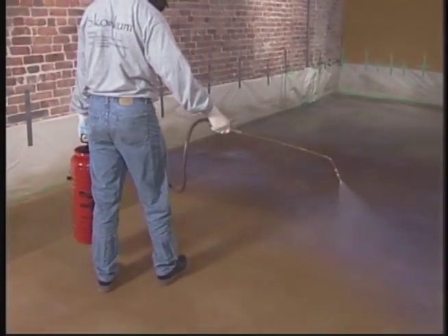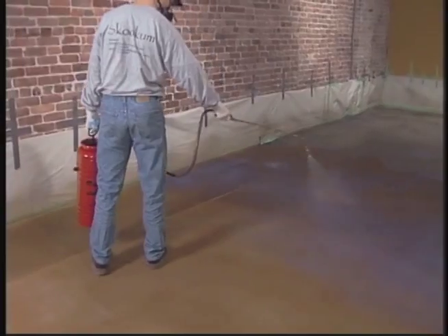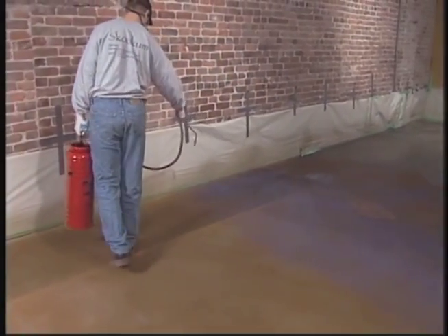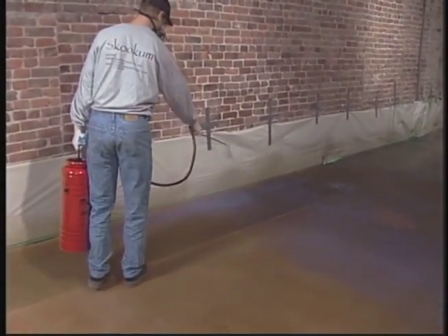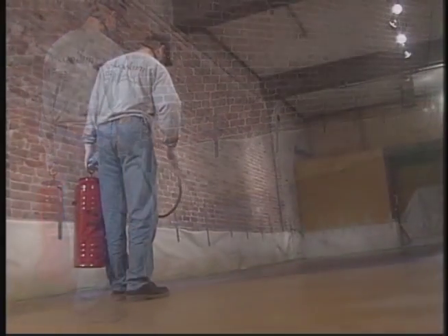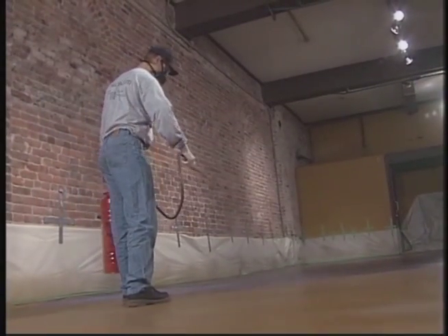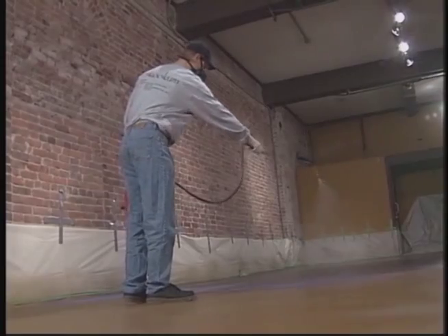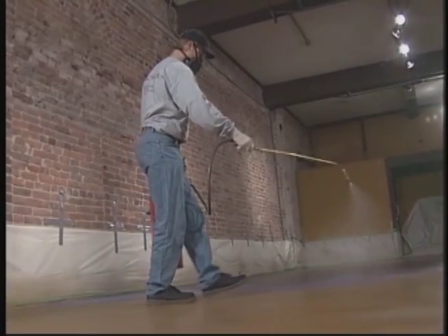The primer or first coat of any application sets the standard for all subsequent coats and should be free from any imperfections. Keep the application of the spray even and mottled. Most sealants or primers are better applied in numerous thin coats rather than one thick one.